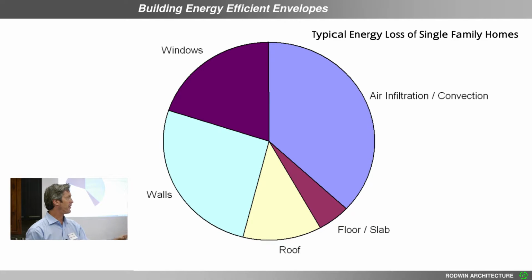Also, the walls themselves, the 2x4s or 2x6s of your walls, are what's called a thermal bridge, and heat actually migrates across them very quickly. So in the center cavity of your stud wall, you may have a great bat of insulation, those big pink fuzzy fiberglass bats, and you might have an R21 wall at that point, meaning that it's a really good energy efficient wall.